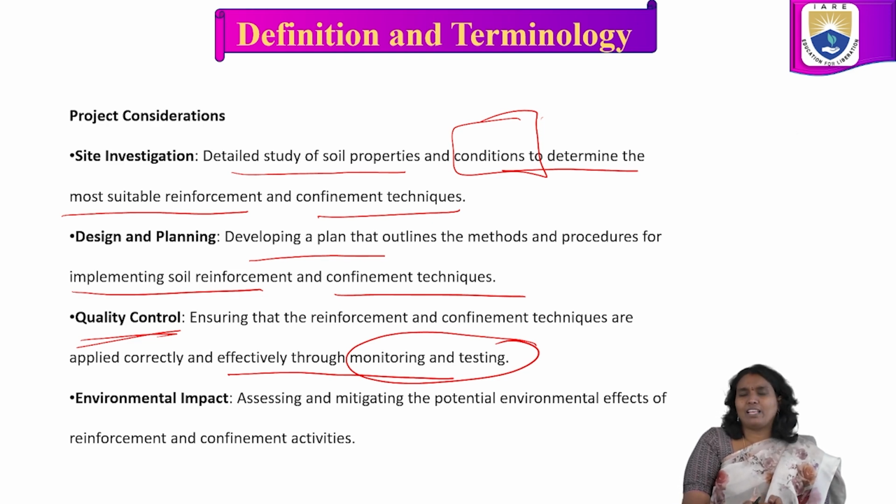Before that, anyway, those tests we are conducting for understanding which technique is suitable, for better understanding of the soil properties. After completion of everything, now we are going to monitor and test after completion of the ground improvement modification process for understanding whether we are getting the desired property or not.